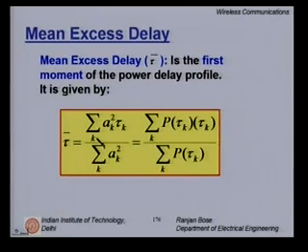Please remember, the small k represents the number of multipath channels. So if we are in a room environment where there are several multipath components, then k can range from 1 to 20 or more, whereas if we are in the outdoor environment where we do not have very many buildings or other reflectors, k can be a smaller number. There could be 6 or 8 significant reflections and hence multipaths.